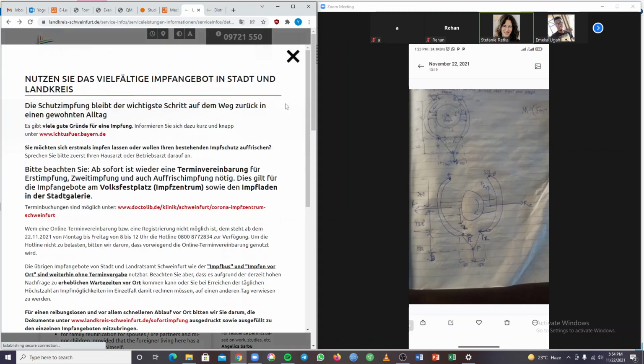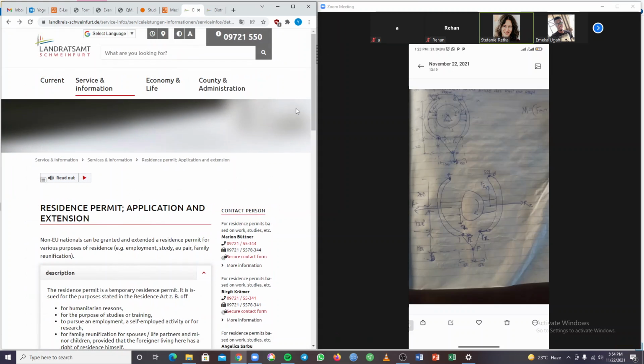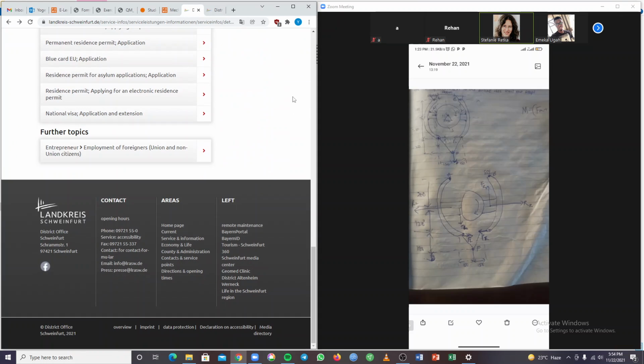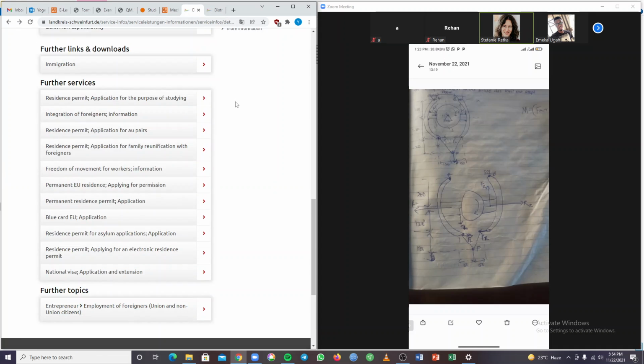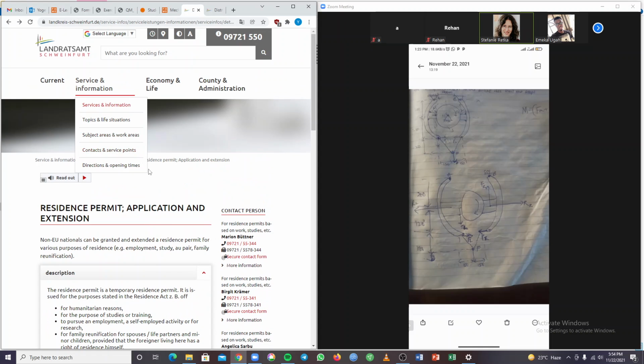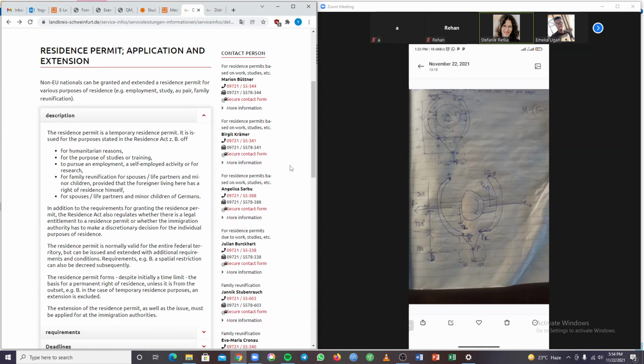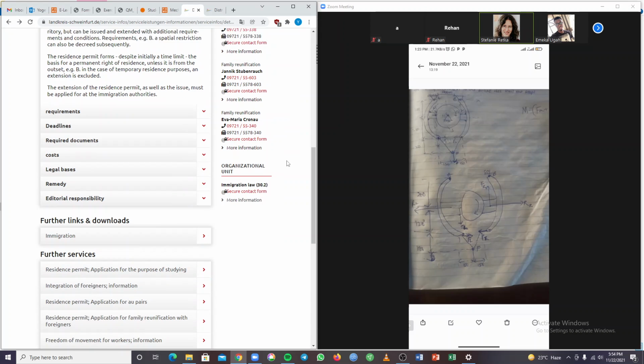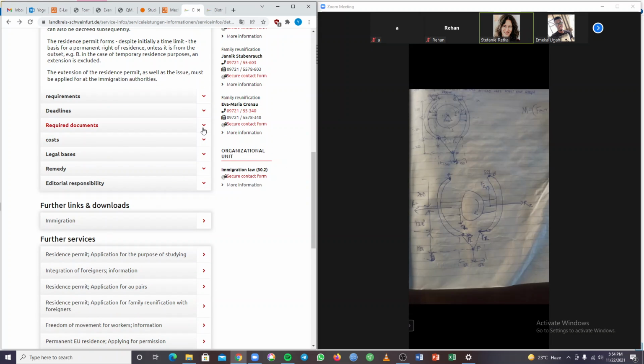And then your second free body diagram would be the free body diagram of one of the braking shoes, like the banded beam on the left, for example. Then you see the hinged support reactions. You would see the forces in the contact point to the wheel, and you would see the rope, the tension in the rope.